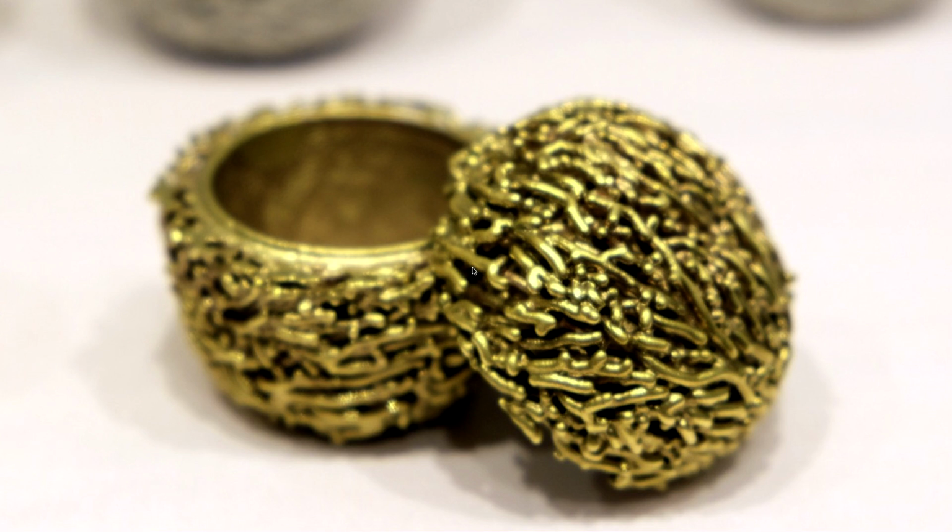The design was really a complex shape for an actual 3D printable object, but if you had just used the Boolean union, just like in other software, that might fail because of all those intersections between the vase and the networks and all those thin branches.